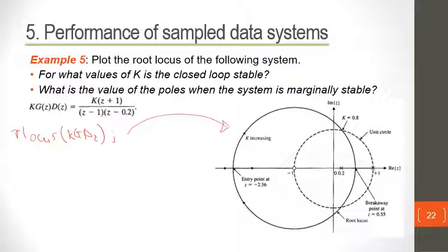The poles start at the closed loop locations of 1 and 2. They would move upward, one moving upwards that way and the second one moving downwards that way, and this will go to infinity. The other one would actually go to the zero.